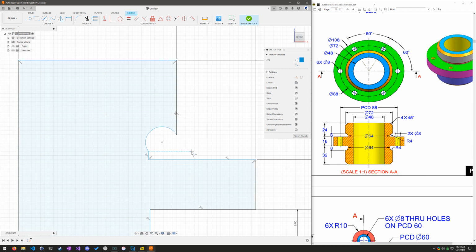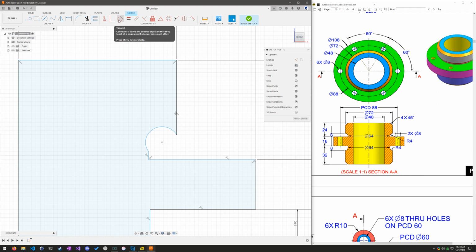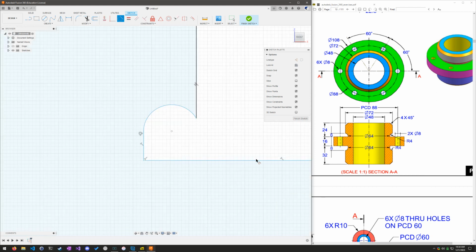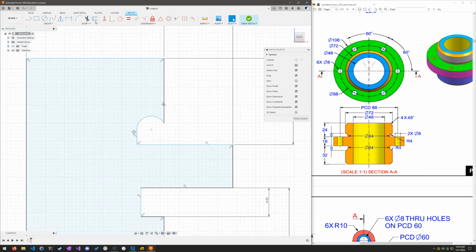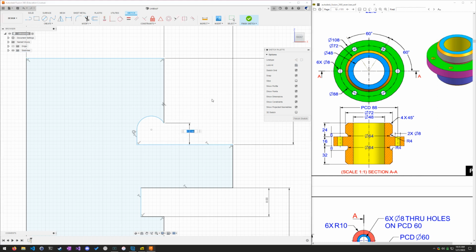Okay. Now I'm going to make the arc tangent, that button there, click to the line. It has a nice smooth transition. Last but not least, I can go ahead and put that 6 back in because it's supposed to be dot to line, or you could do dot to dot, but either way, it should work. 6, enter. There you go.